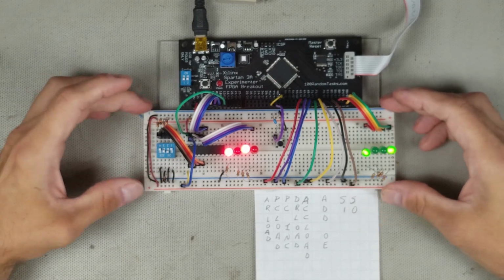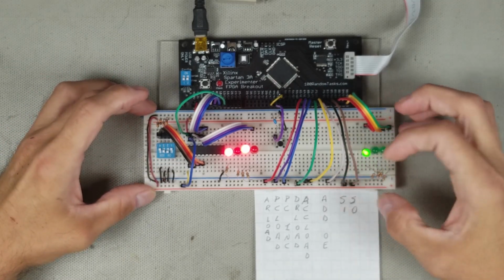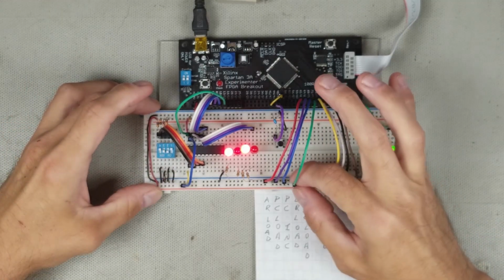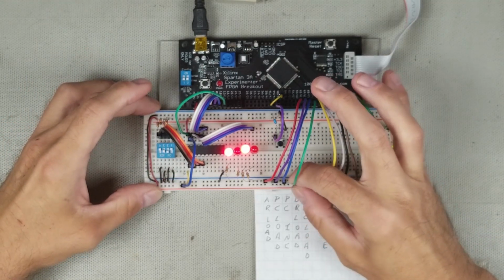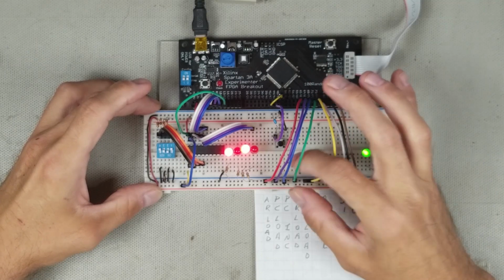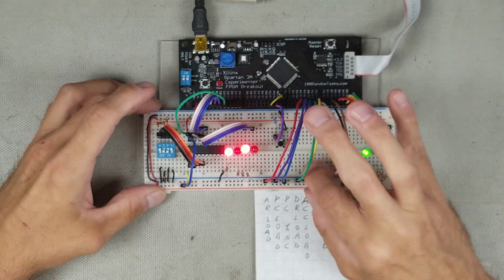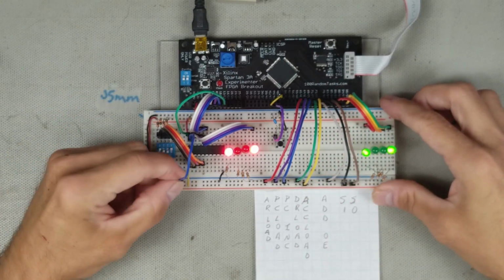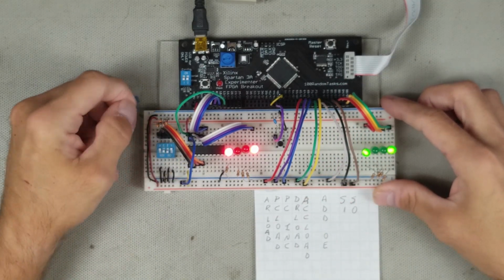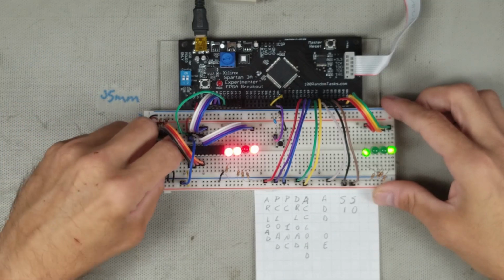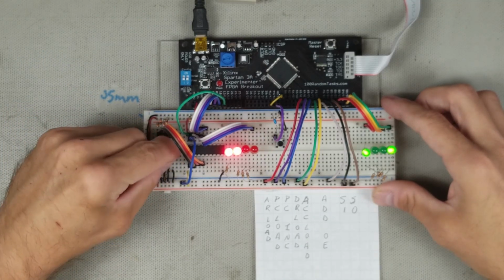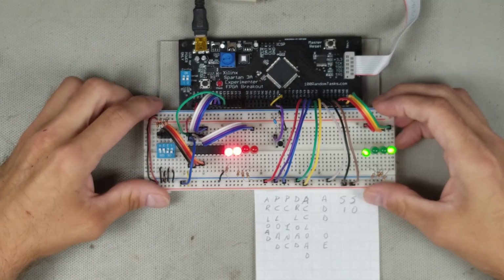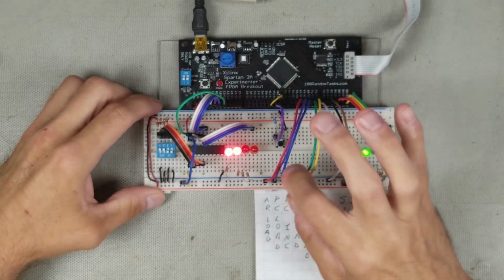Next I'll load the accumulator with 1100. To do that, I'll set the select lines to 11 to access the external bus, set the DR load to 0, and the accumulator load to 1. The read-write to 0, and set the dip switches to 1100. And cycle the clock. I'll increment the program counter value now to 0110.